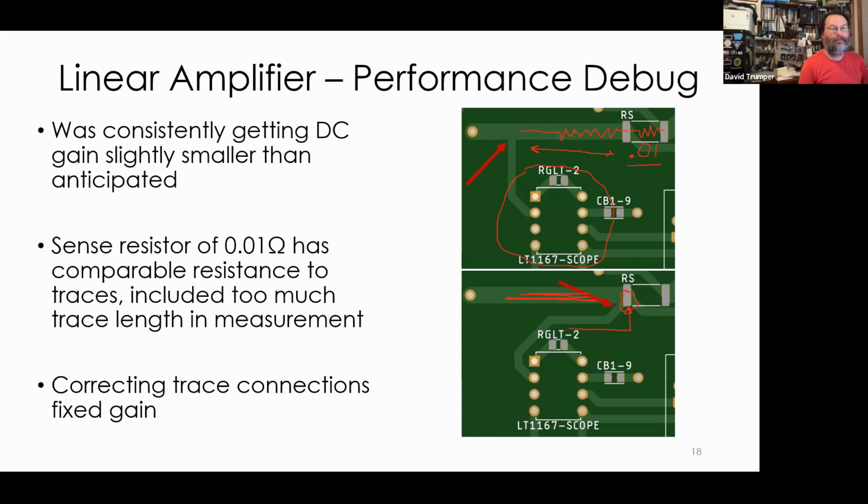And that was a subtle one to find out, especially in Zoom land where I couldn't walk in and see the actual PC board. And I think you had to actually point an iPhone at it for me or something. I forget. Yeah, trying to debug hardware remotely is crazy. Is that clear to people what the small fix was? That was a 20% calibration error, because I think you bought a 0.1% accurate resistor. I did. Yep. And we were off by 20% in our calibration because of that small PC board layout error.